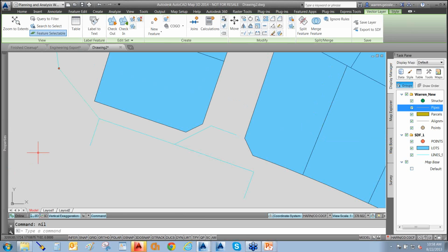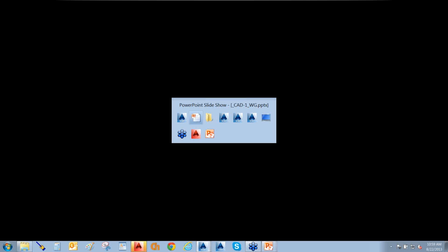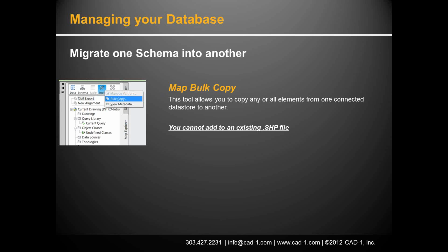You'll perform the join. Now, the cool thing is that you can join the data off of shapefiles, off of SDF files, off of Access databases, as much as I hate to say this, Excel spreadsheets, or a lot of other sources. You cannot edit any of the join data, but there's a lot of things you can use it for, queries and theme mapping and everything else. So hopefully that answers your question. It looks like it does, because it looks like you know the join command in Esri. We've got the exact same thing. Chris says, great, thanks. Thank you, Chris.